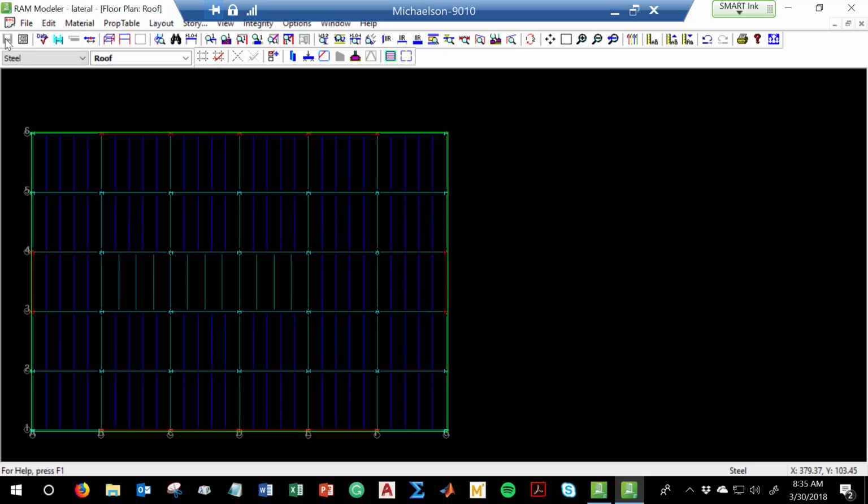Now, this is what you're not going to like, but it's going to add a little bit of work, and there's really no other way around this because lateral design, in its nature, is really, really complicated. I propose that for a building like this, the easiest way to design your lateral system is to make a few guesses as to your member sizes and then start adjusting accordingly. What I mean by that is this.